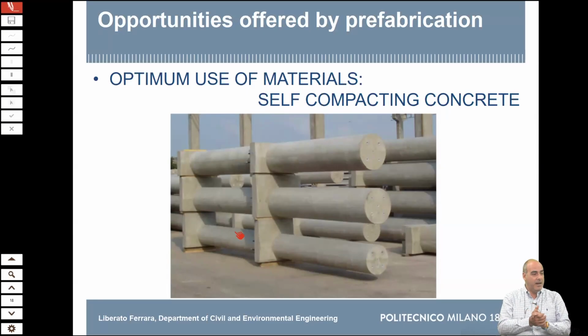We were working in a European project, so things were managed pretty well. The structure was built for research purposes. We had 5-meter high columns, which were cast with the pump from the top. The stirrups were designed for earthquake testing, so there was quite tight stirrup spacing, at least at the bottom and at the top of the column. And they were tied, but the force of the concrete falling from 5 meters, in some cases, displaced the stirrups, even if everything was done correctly.